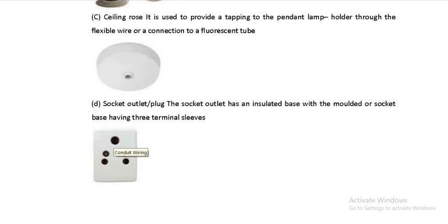If there is any kind of fault in your appliance, and let us say a fault current is flowing through the appliance, you do not want that fault current to flow through the operator, whoever it may be, your mother, yourself, your father, whoever it is. He or she should be saved from the electric shock. That is why this earthing connection is there.